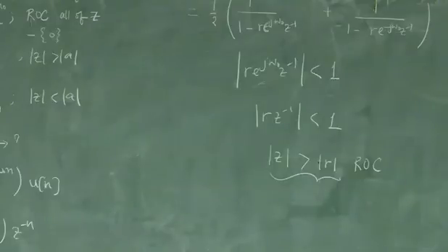So we first find the places where it's going to become infinite, typically by looking at where the denominator goes to 0. Those z's where the denominator goes to 0, we call poles, and the places where the numerator becomes 0, we call zeros. So hopefully that is clear.